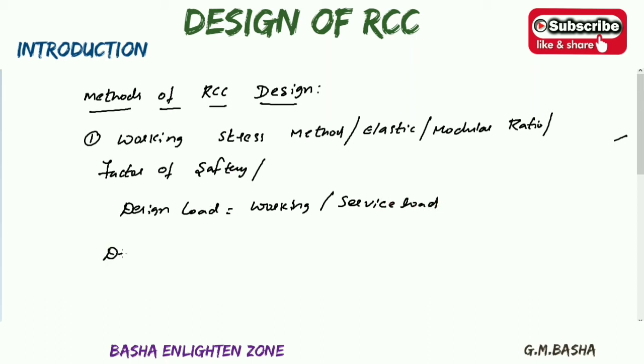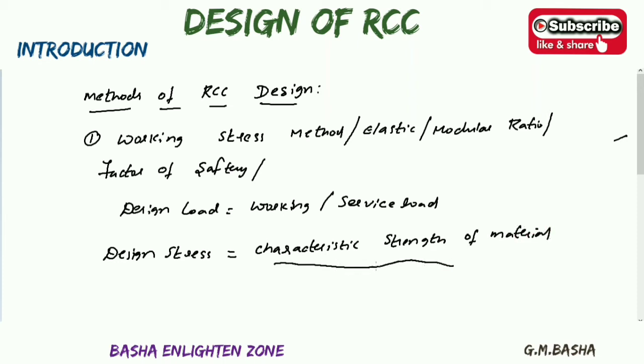And design stresses, meaning allowable or permissible stresses, will be equal to the characteristic strength of material divided by the factor of safety.